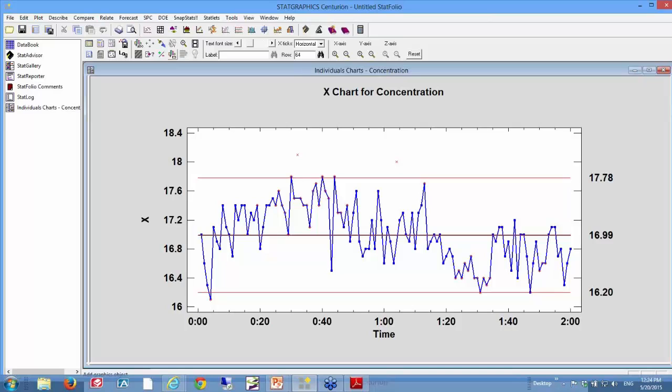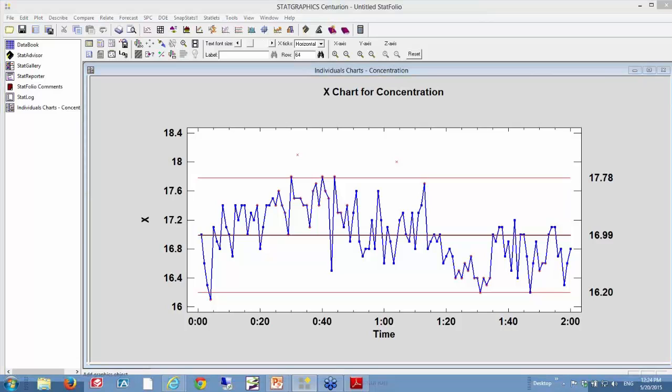Another question on acceptance charts. If a data point representing a manufactured batch falls within the control limits, what claim can I make with regard to that batch? For example, with 95% confidence, there's no more than a 3% chance the batch fails to meet specification.